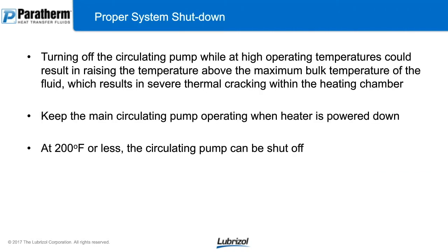Proper system shutdown. Now this is really key here. If you turn the circulating pump off while you're at high operating temperatures, you're actually going to raise the temperature above the max bulk temperature of the fluid and have severe thermal cracking within the heating chamber.